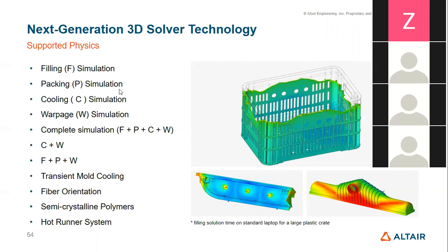Because if the machine screw comes back after the filling, due to the vacuum created there, it sucks back some molten material from the die. And one more reason for the packing is just to compress the molten plastic into the die. So that holding is the packing simulation. In the holding, it will show you the grain structure of your component, how your grain structure is behaving. And next one is the cooling.